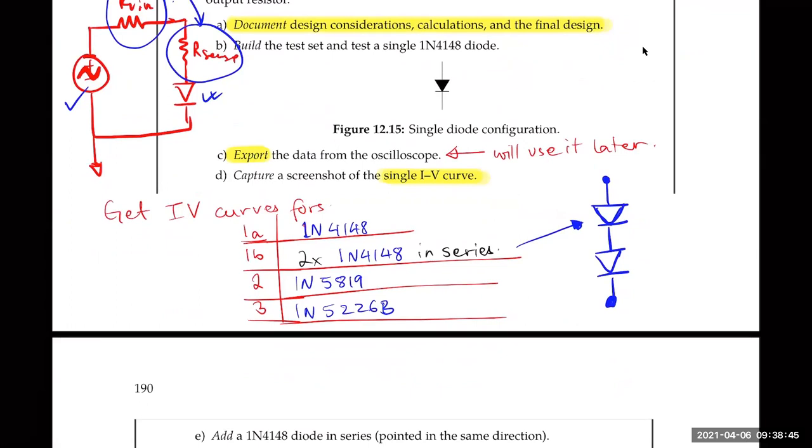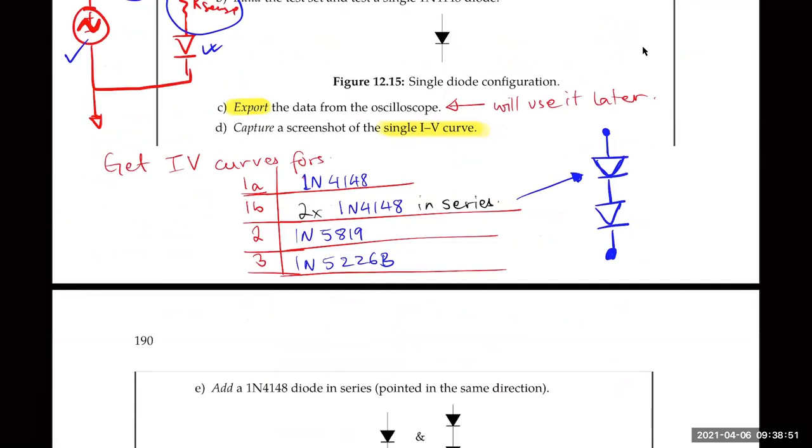Okay, so one thing I haven't told you about is the Zener diode. I haven't talked about the types of diodes. You can look this up in the lecture video and in the lab manual. But one important feature of the Zener diode that I should mention here is its Zener breakdown. What I've said so far is that diodes will not conduct any current unless they're in forward bias. But if you keep increasing the reverse bias, after some point there will be a breakdown voltage beyond which the diode will start conducting current.